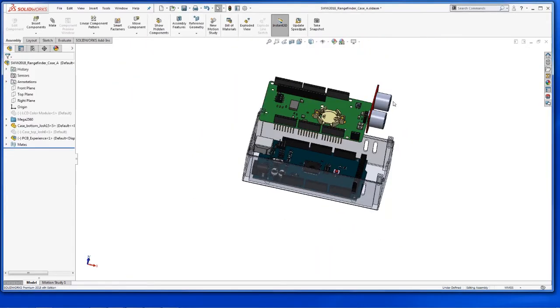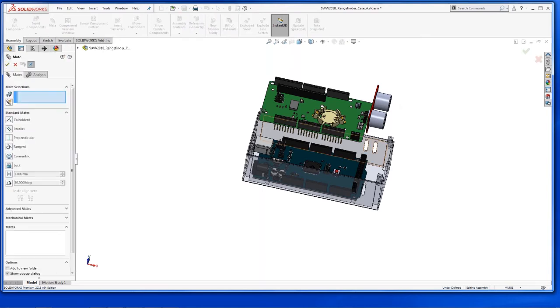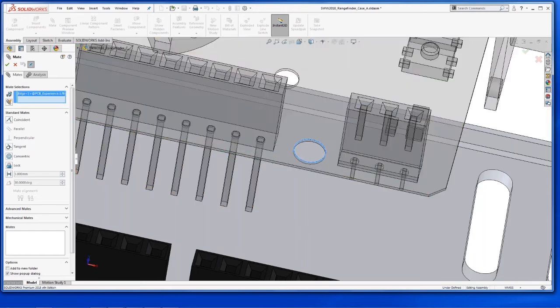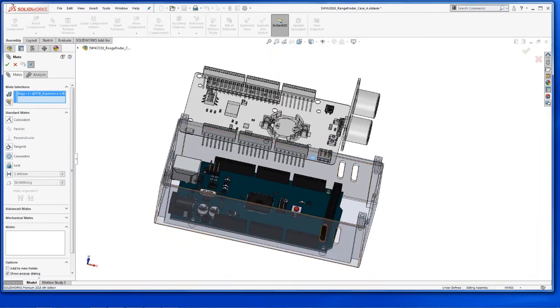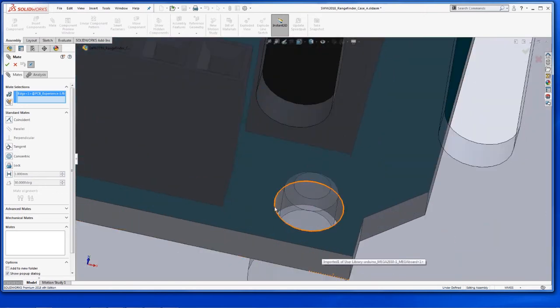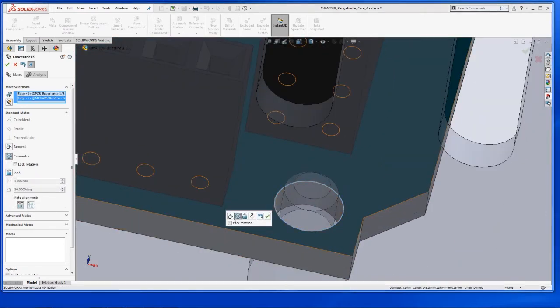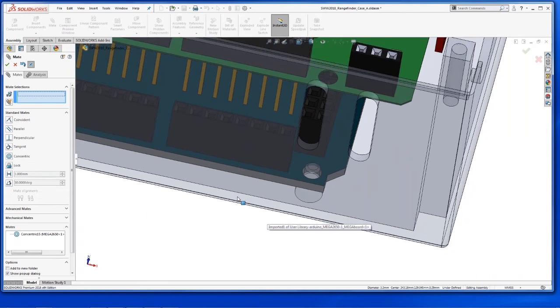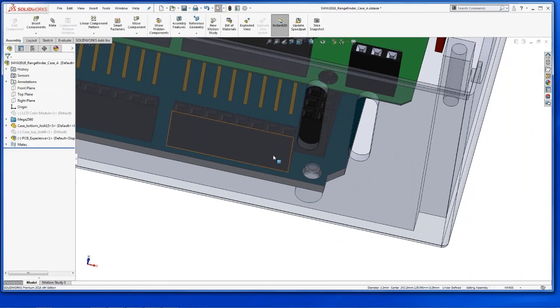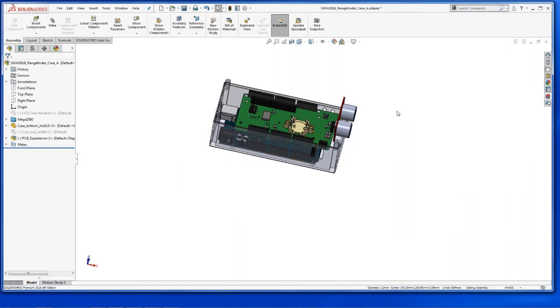Now we want to reference this new assembly to features of our existing SOLIDWORKS assembly, which also has an existing PCB in it. We'll simply just make some mate references for some features on our existing assembly and our new assembly. Okay. Here we're just doing a simple concentric mate to line up the holes for the assembly. Okay. Now additionally, we need to set the offset height between the two boards.